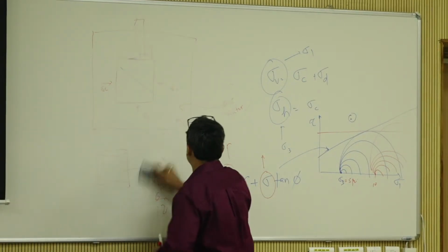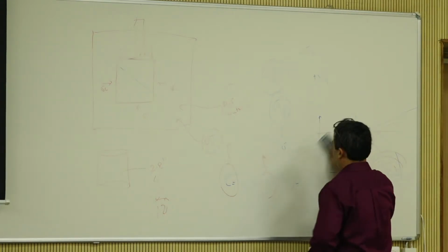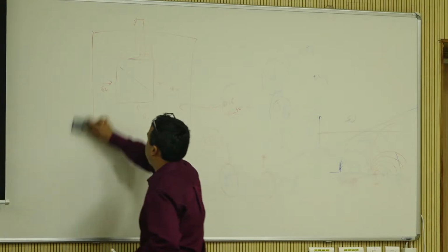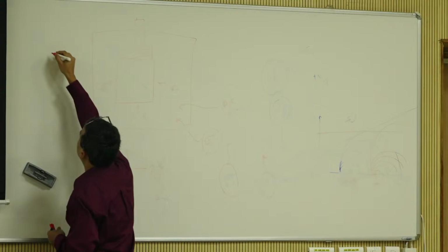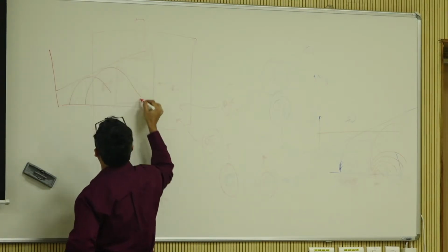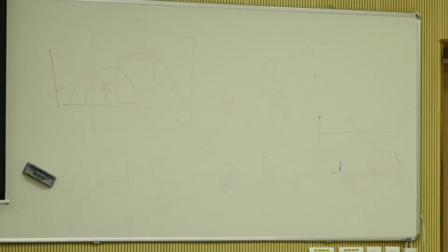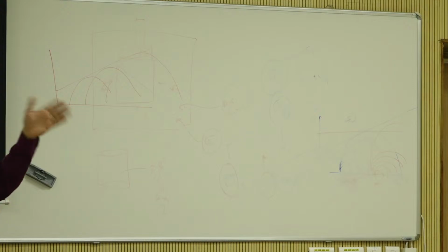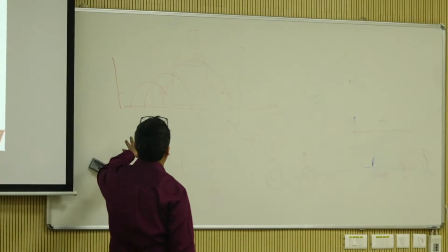But the bottom line is you are going to use a Mohr-Coulomb failure envelope. So just do this, maybe like one circle here, one circle here, one circle here, and that's what typical triaxial testing does, right? When you go into pure geotech, you can go into all the different forms like unconsolidated undrained, consolidated undrained, consolidated drained, unconfined compression and stuff like that.